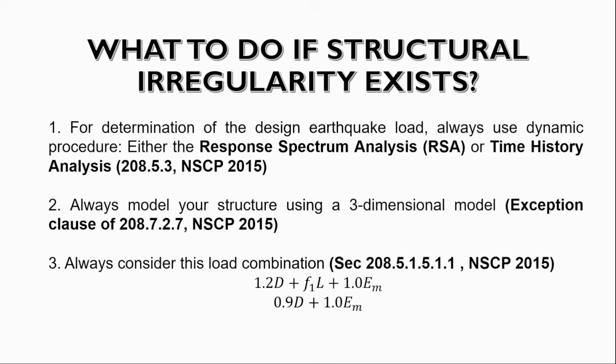Just remember these two: if irregularity exists, number one, we use the dynamic procedure, and number two, we use a three-dimensional model.